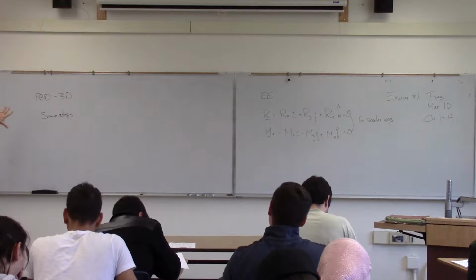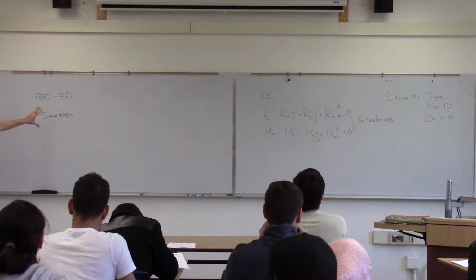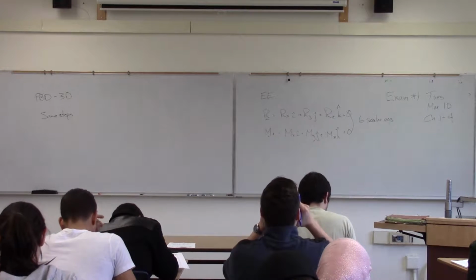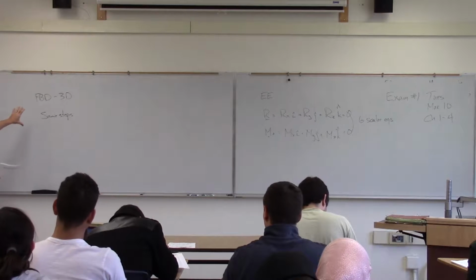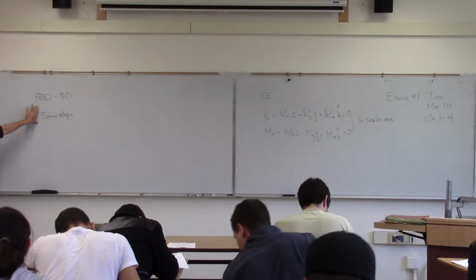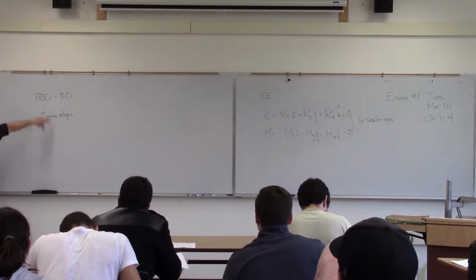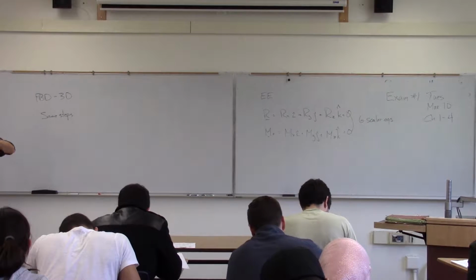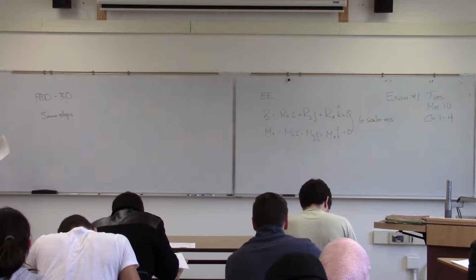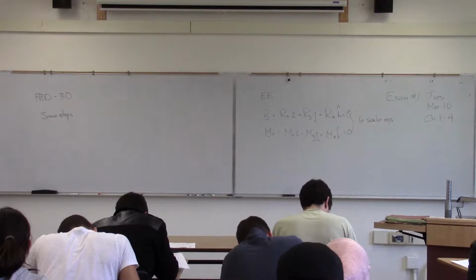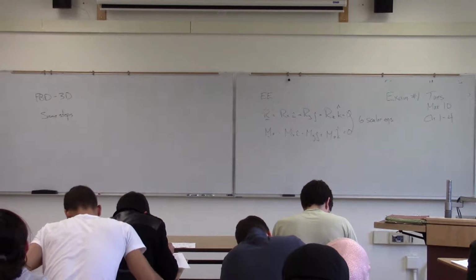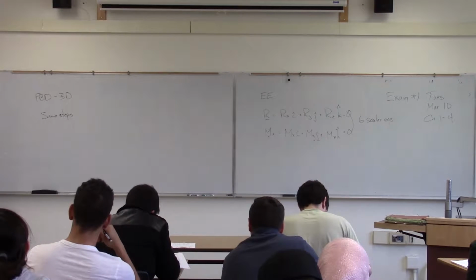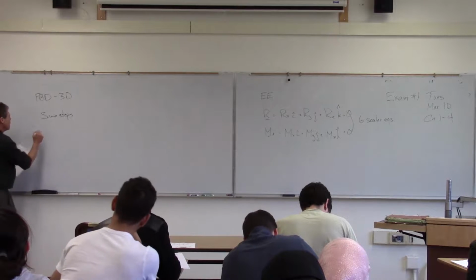Okay? So we're going to be doing trusses and stuff like that. So there's going to be internal forces in those truss members. We don't care about those because, again, when we talked about setting up our rigid body, it was what was going on externally. So what we're going to be interested in is drawing that external boundary, putting all the forces on it, putting dimensions on it, putting a Cartesian system on it, and that sort of thing. So it's the same steps that we've done before.